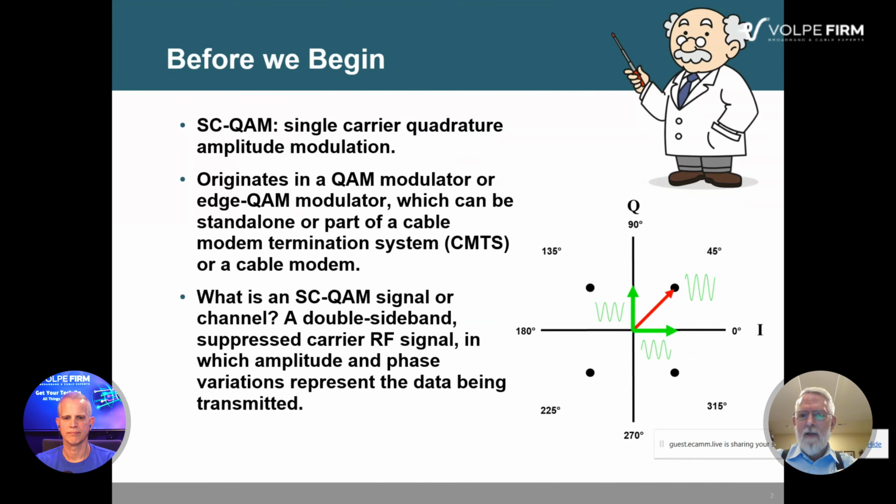And what I've got on there are some angles. I show the I and the Q lines on there, and you can see the arrows, which are vectors that represent the amplitude or the magnitude of each. So you can see that little cosine wave and a sine wave next to the two green arrows, and the vector sum of those two is the red arrow.